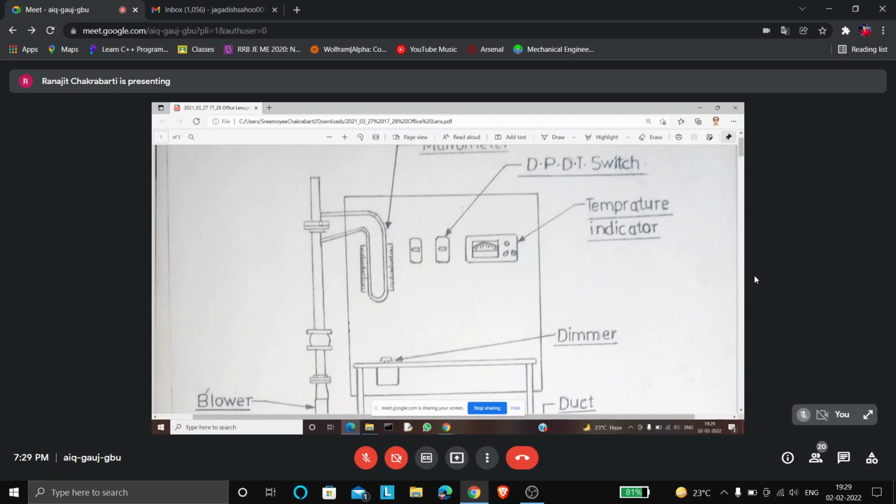Pressure here is high, static pressure, here it is low. So this surface will be lowered and this surface will be upward. And the difference between these two surfaces is measured by a scale. Measuring that difference, there is a formula by using which we can find out how much is the air flow through this orifice.